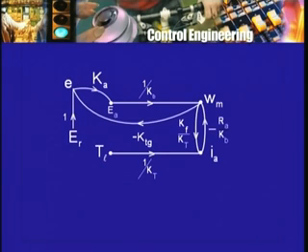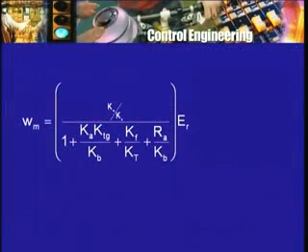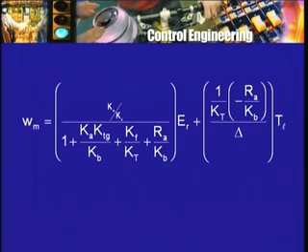So can I then write down, and this forward path, does it touch both the loops? Yes, because it ends at the node omega m, therefore it touches both the loops L1 and L2. Therefore what will be in the numerator multiplying the forward path gain? Only 1. And so I can now do that very quickly, and I can write this as, therefore this is the minus sign. Normally there is a plus sign here. Okay, let me write here plus sign, because this is the normal rule, plus. Then the bracketed expression may have a minus sign, which it does.